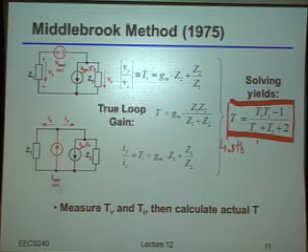Okay? So again, keep this in mind because these kind of accuracy issues, I mentioned it here in the context of this feedback circuit, but this pops up all the time. There's a lot of things that you will care about that could be on the edge of the nominal accuracy of the simulator. And so you better actually play around with those parameters to ensure that what you're seeing is real and not just some artifact of numerical garbage coming from the calculations.